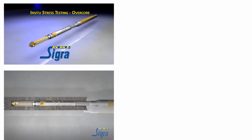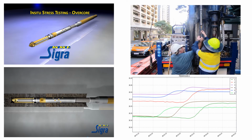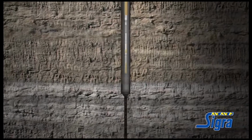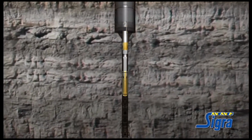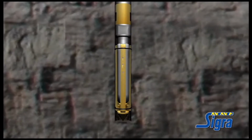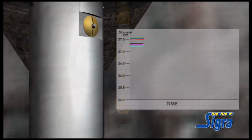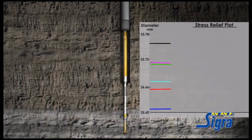Overcoring is a process by which stress is relieved around some device that measures rock strain or deformation. The common process is to overcore around a pilot hole containing an overcore cell and to measure the deformation as this occurs. This video shows the SIGRA IST 2D cell being set into a pilot hole drilled ahead of an HQ core hole. The core barrel is then lowered and overcoring takes place to relieve the stresses on the core, while the pilot hole deformation is measured.